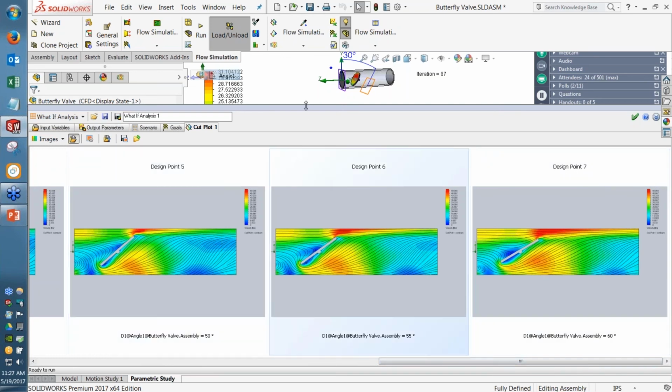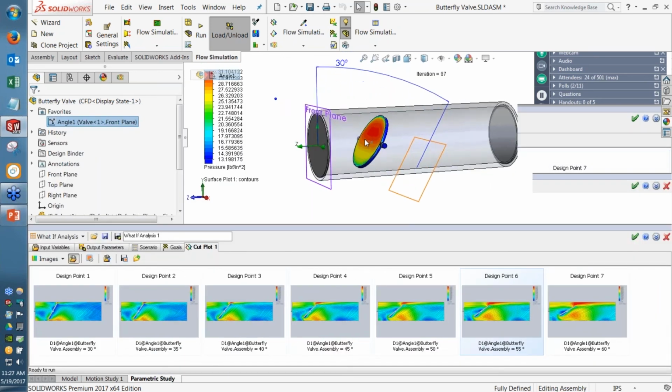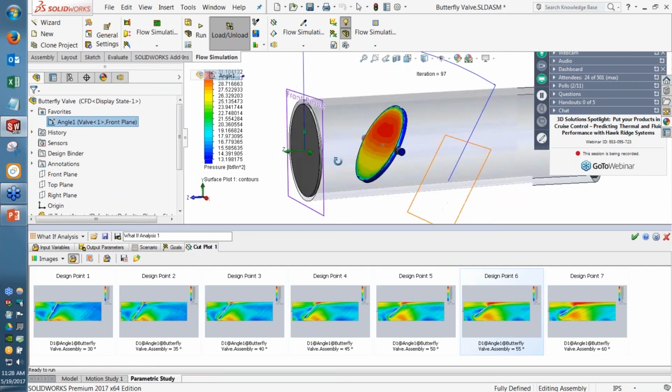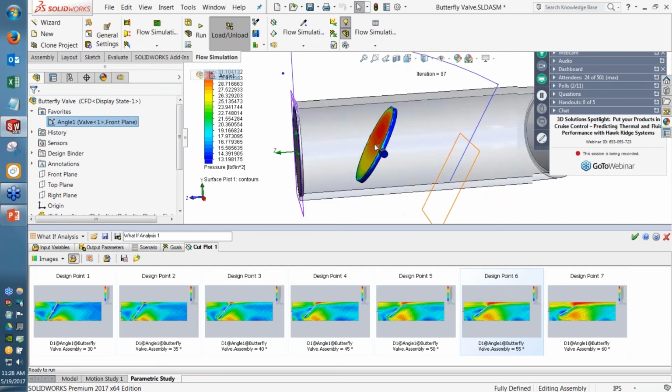I may have been able to find that from the motion study we did earlier. In this case, I looked it up, and it's about 1 pound-inch. So about a pound-inch of torque is from the weight. We'd be trying to pull this sort of in a counterclockwise way back towards the vertical position. So at what position here is the torque from the flow going to match that?